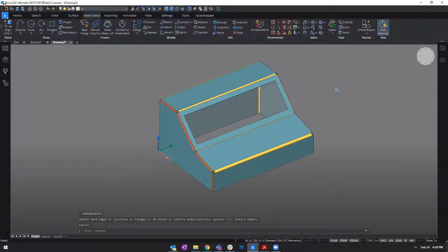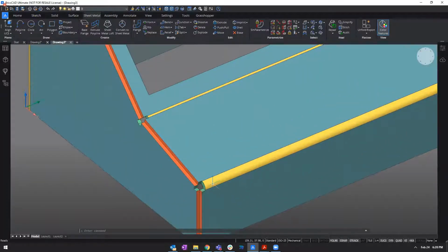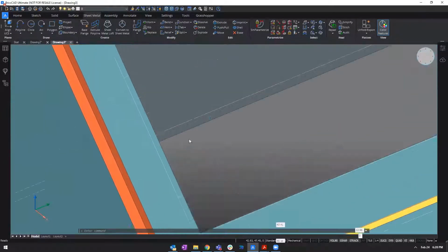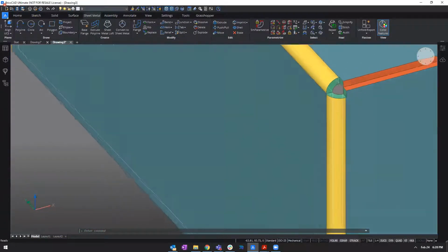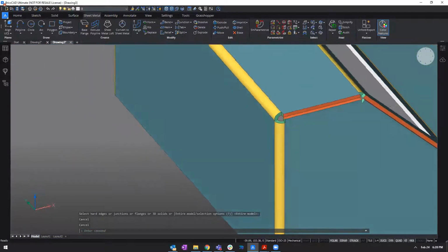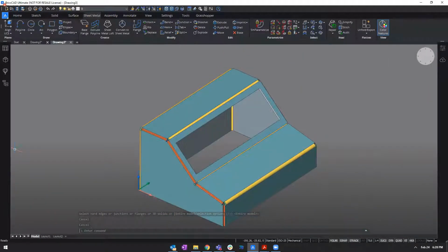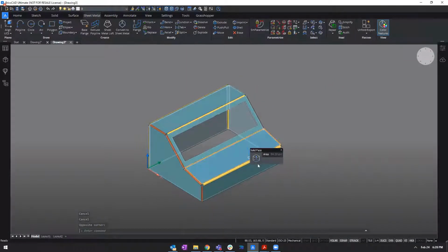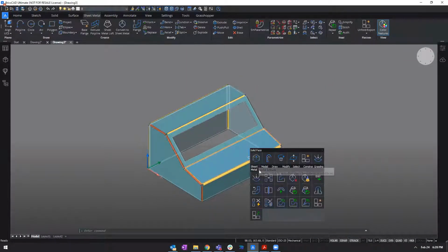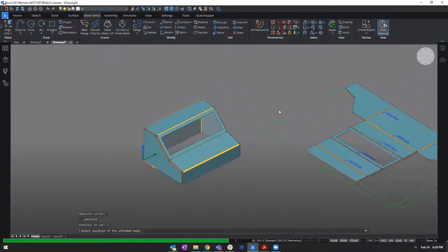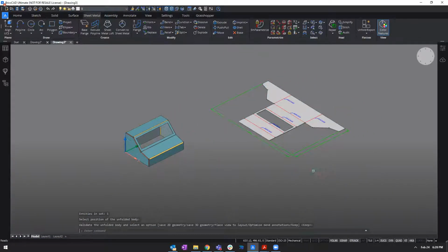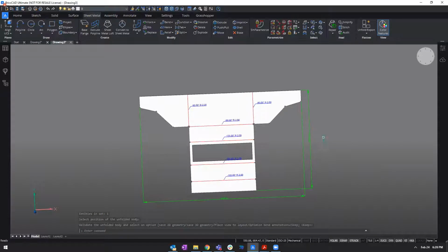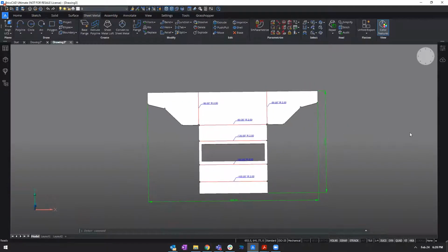To do that, I will start off by turning these junctions into bends. By the way, before I do that, I just want to make sure to check my mechanical browser and see if everything is okay here. So I can see currently that all my flanges and bends and junctions, they're all colored in white, which is good. However, it might occur that it turns red, and that means that there's something wrong with it. For example, a sort of clash between parts.